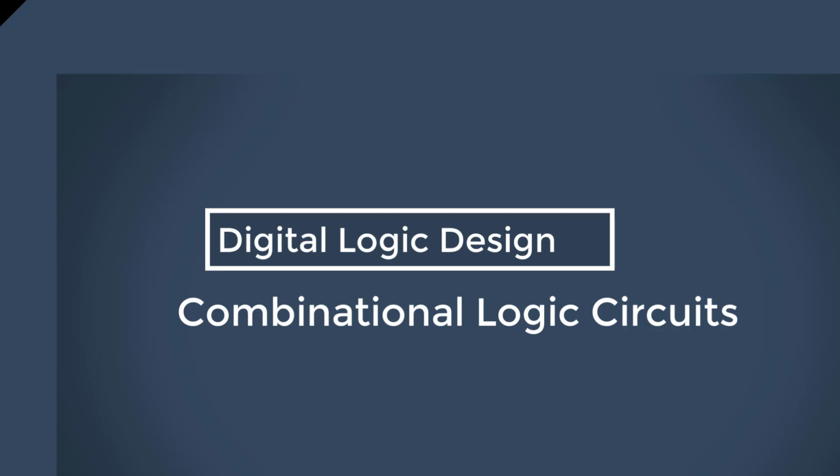One of the basic combinational logic circuits is the adder. These are all arithmetic circuits which perform all the arithmetic operations. So let's first look into the basic combinational logic circuit, that is a half adder followed by a half subtractor, and then once we get hold of half adder and a subtractor, we can analyze the design of a full adder and a full subtractor, followed by carry ripple adders and carry look ahead adders.